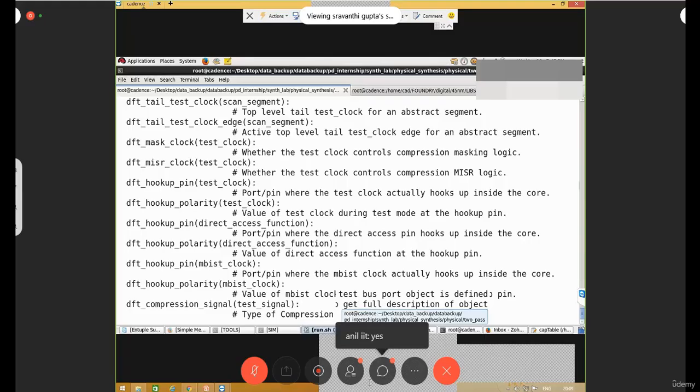So what I was telling is there are two important inputs for physical synthesis, unlike logical synthesis. In logical synthesis we give one primary major input, that is RTL, and we expect the netlist from the RTL. Other constraints, design constraints, we give as per the architecture specification. When you come to physical synthesis, we are giving two additional important inputs: the LEF and DEF files.